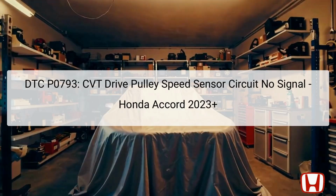The specific diagnostic trouble code DTC P0793 indicates a problem related to the CVT, continuously variable transmission, drive pulley speed sensor circuit in the Honda Accord 2023 and later models. This error occurs when the TCM, transmission control module, detects that the rotation speed measured by the CVT drive pulley speed sensor is either below a specified threshold or indicates an abnormality.